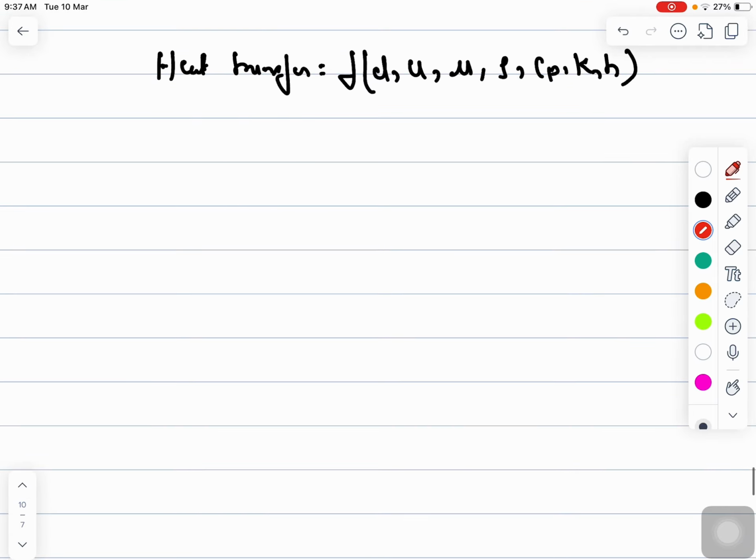So the equation describing the heat transfer process can be written as a function of, let's say, heat transfer coefficient h, diameter of pipe, here I'll use the notation capital D, and then U, viscosity, density, Cp and k, that will be equal to 0.